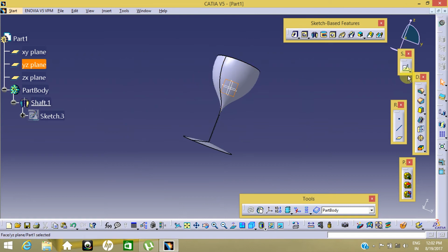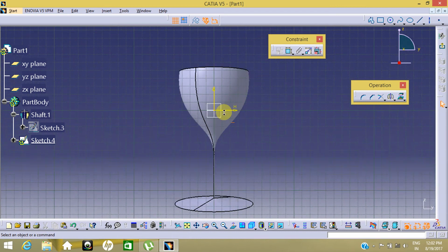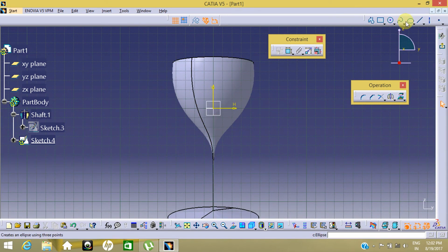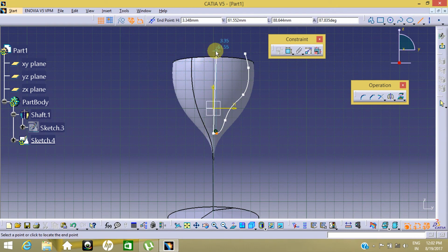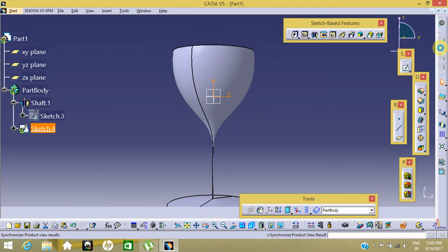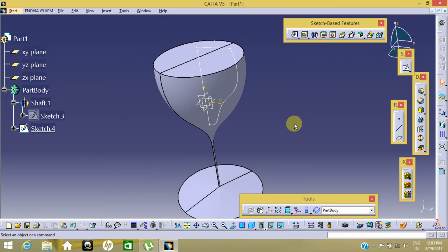So select the groove command here and select your sketch. Again, it's providing your first angle that will rotate your sketch in clockwise direction. So now it's asking for its axis, so select the axis here and make an OK. So you will see a material has been removed from the body. So this is a groove command which you see here. Okay, so these types of commands are generally used to add material and remove material by two different methods.